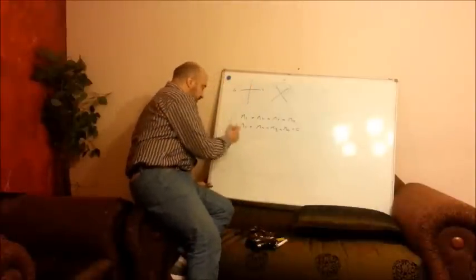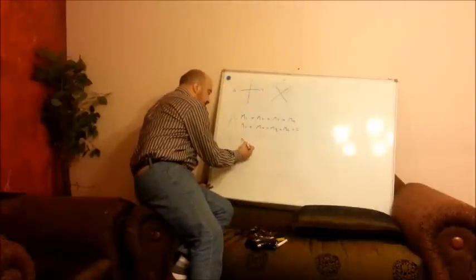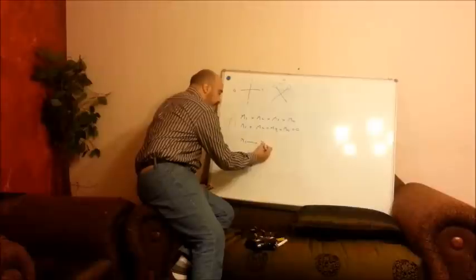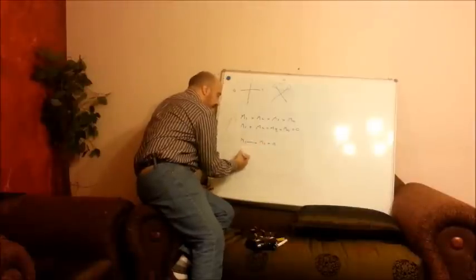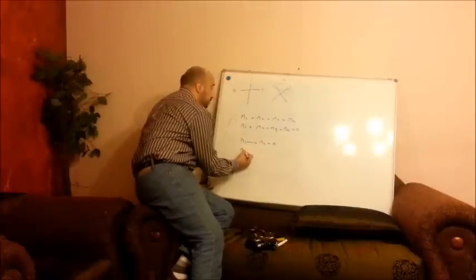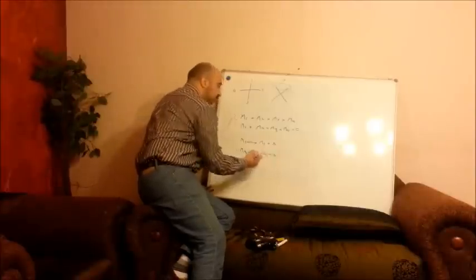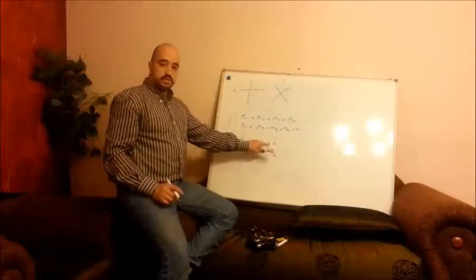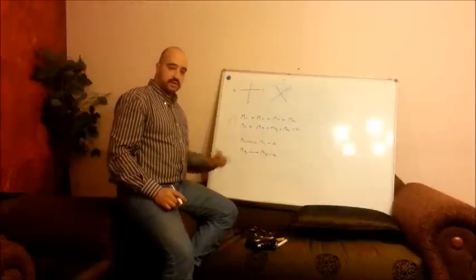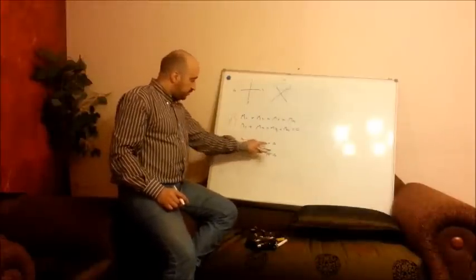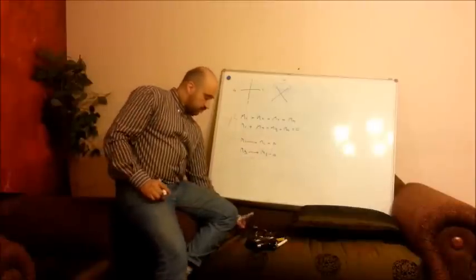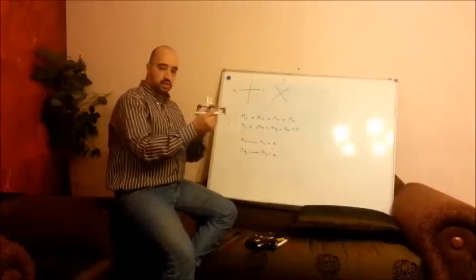So we can safely increase one of them and safely decrease the other, as long as we use the same amount for increase and decrease. Because if we violate this rule, the quad will start to rotate.